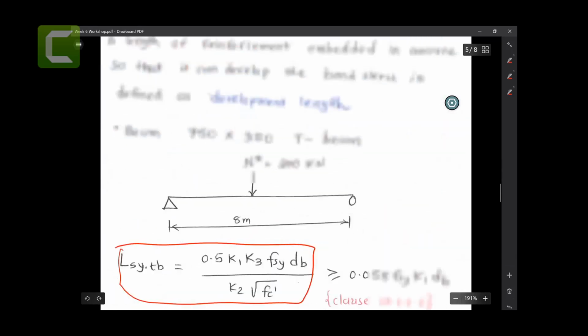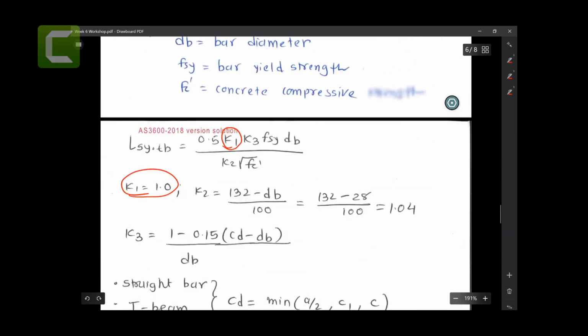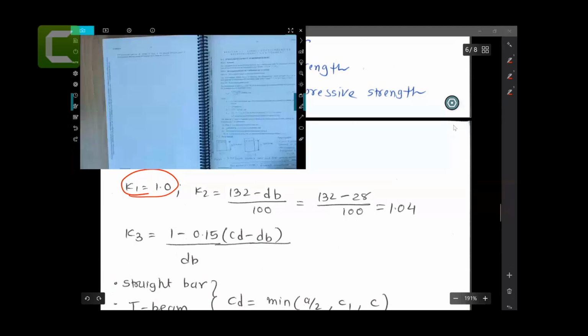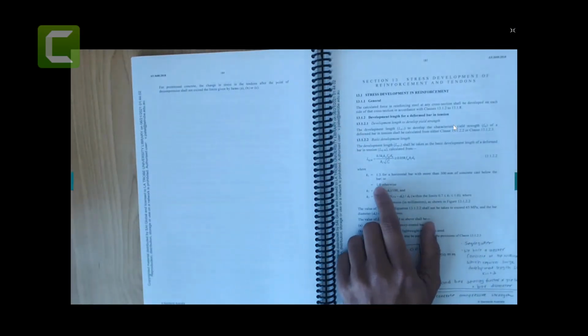That's pretty much k1 done, not that hard. We don't receive the penalty, meaning this is a 30% penalty that the standards want you to apply if you have more concrete sitting down below. So we don't have the penalty. We are happy, not bad.